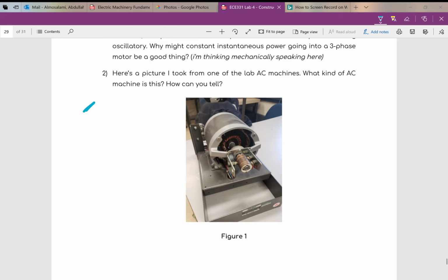However, there's a few other dead giveaways. Okay, so first of all, if you conclude that this is an induction machine, and there is a way to do that, I'll explain that in a second. But if you conclude that this is an induction machine, then induction machines have only two kinds of rotors. Either it's a cage rotor or it's a wound rotor. And I don't know about you, but these over here look like copper. That there looks like copper to me, which means windings, which means the rotor has windings. And so this is clearly a wound rotor.